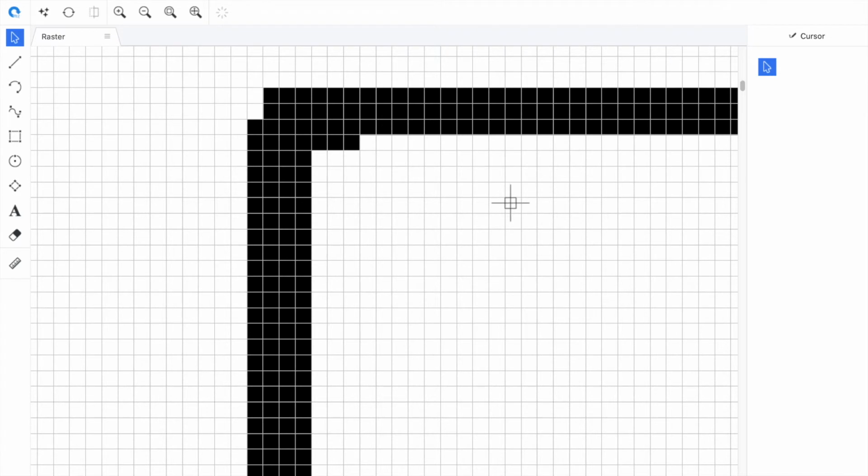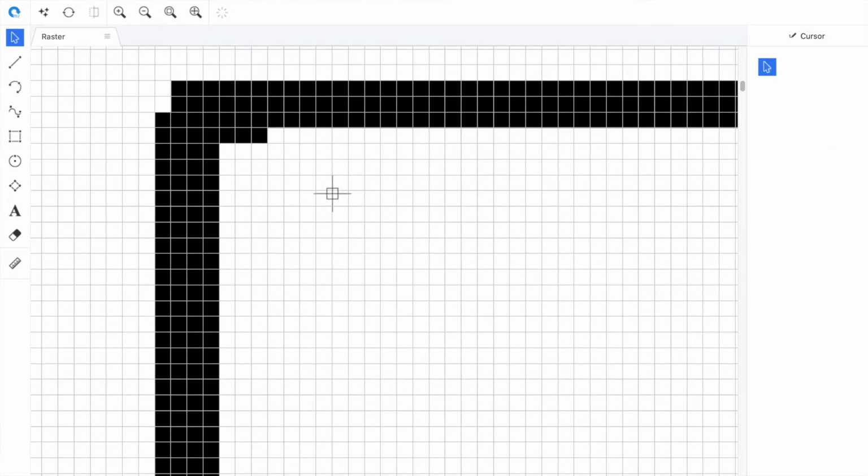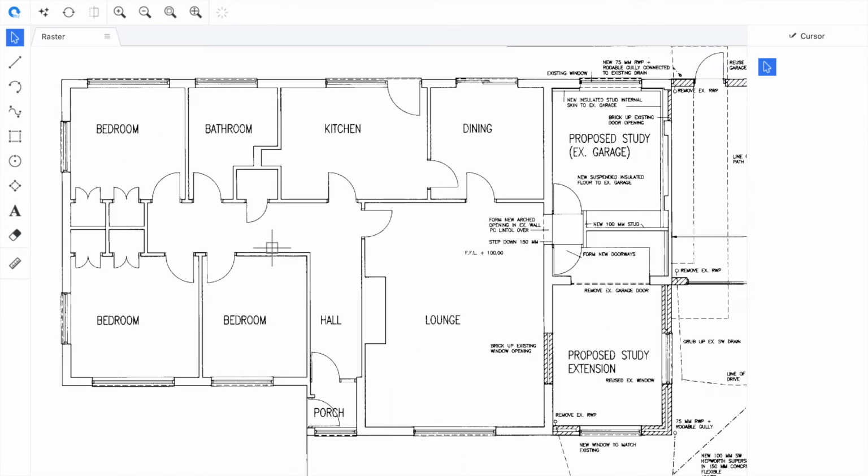So if we're giving the conversion software ScanCAD a raster image, then what you'd want is the conversion to trace accurately the original image. That's different to saying, let's say, for example, I want this wall to be exactly 20 feet. Well, that's fine, but you need to ensure that the original drawing has the correct tolerance, the correct scaling, and so on. And then the conversion software can take it from there.